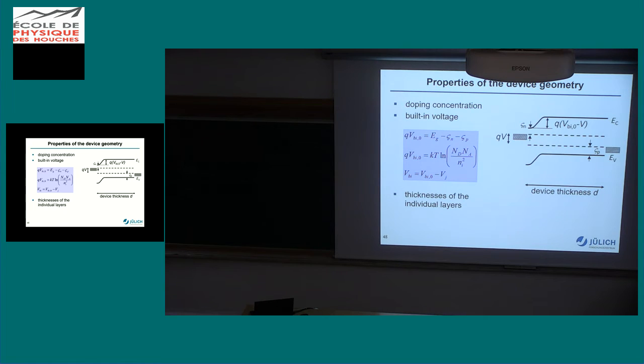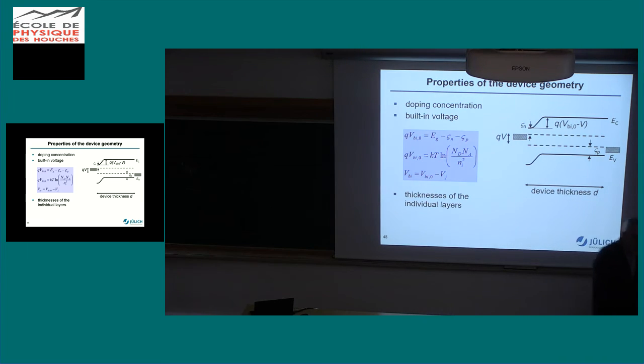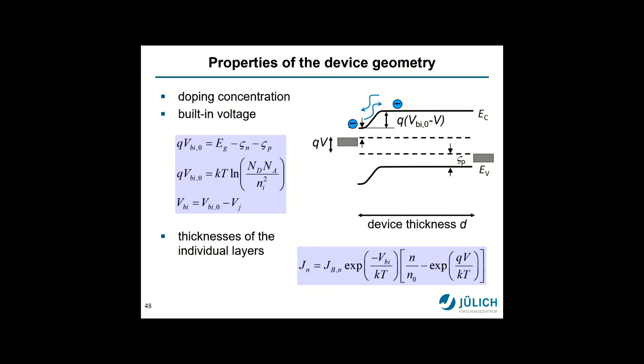So anyway, you have a capacitor, and the capacitor is really hidden there in the space charge region, because you make the space charge region smaller. And how do you do that? By just removing charges from the space charge region. That's a capacitor that is there to enable that you have that voltage difference. In between these two plates, somewhere you have to accommodate these charges or withdraw these charges. Okay, that's one lesson. Always search for the capacitor in your solar cell. That's always a good idea.